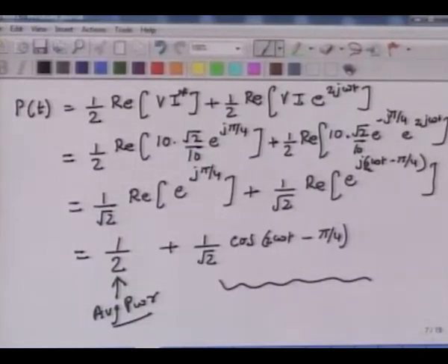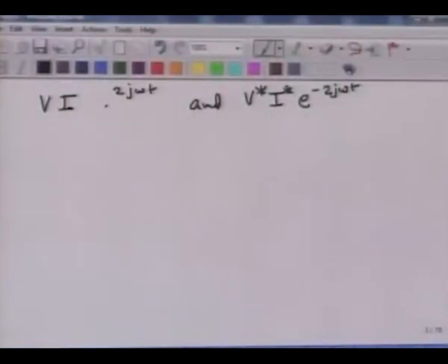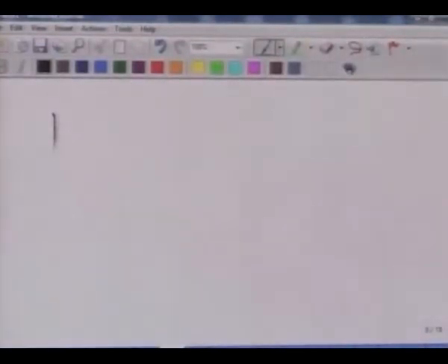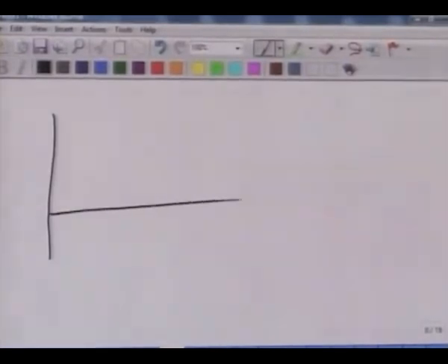Now if you plot this entire expression, you will see that the instantaneous power, not the average power averaged over a whole cycle, can become positive and also negative. But the fact that it's becoming negative does not mean it's getting absorbed permanently somewhere. It's getting saved into the system, and then dumped back into the system, back and forth. So if I plot it, my graph will look something like this.